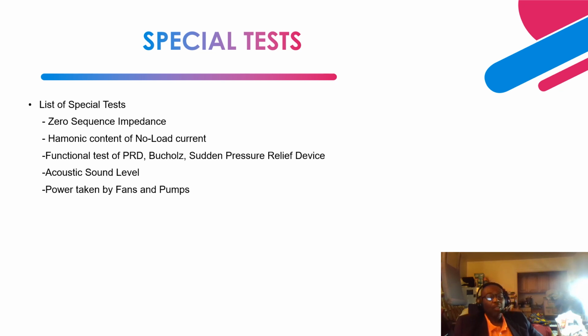As you know, the positive sequence current is equal to V over Z0 plus Z1 plus Z2. The Z0 part is the zero sequence impedance, Z1 is the positive sequence impedance, and Z2 is the negative sequence impedance, then plus 3ZN. If you have the transformer connected to any neutral ground resistance, that is the 3ZN part of the bottom part of this equation.